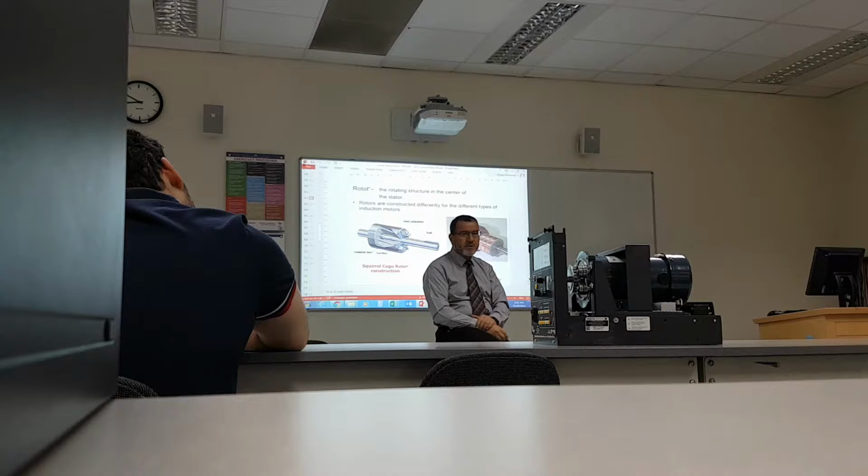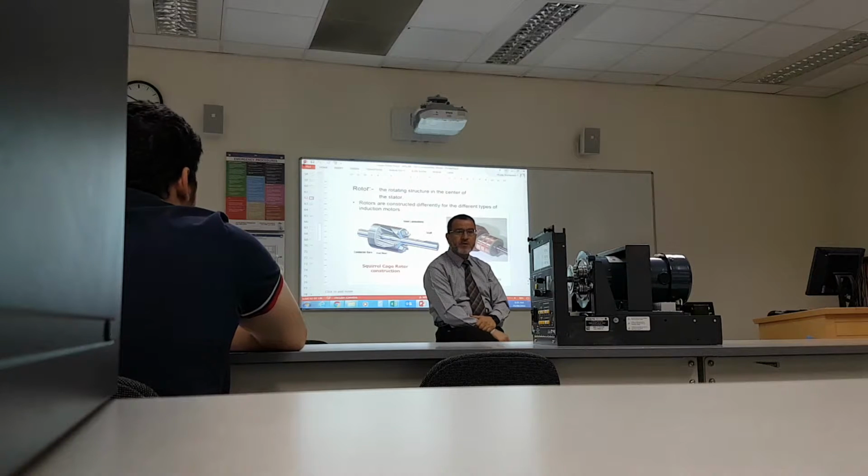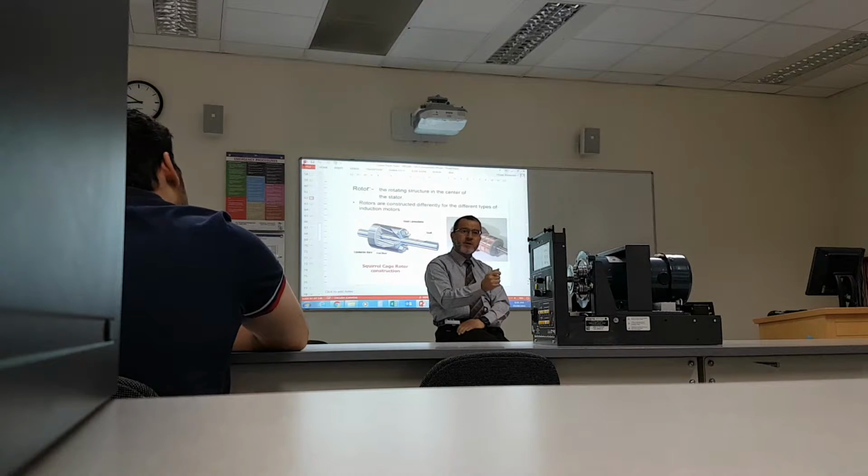But with synchronous motors, some are not even designed to be loaded with anything. They are just used as capacitors for correcting the power factor. For power factor correction. Because you can run a synchronous motor as normally excited, underexcited, or overexcited.